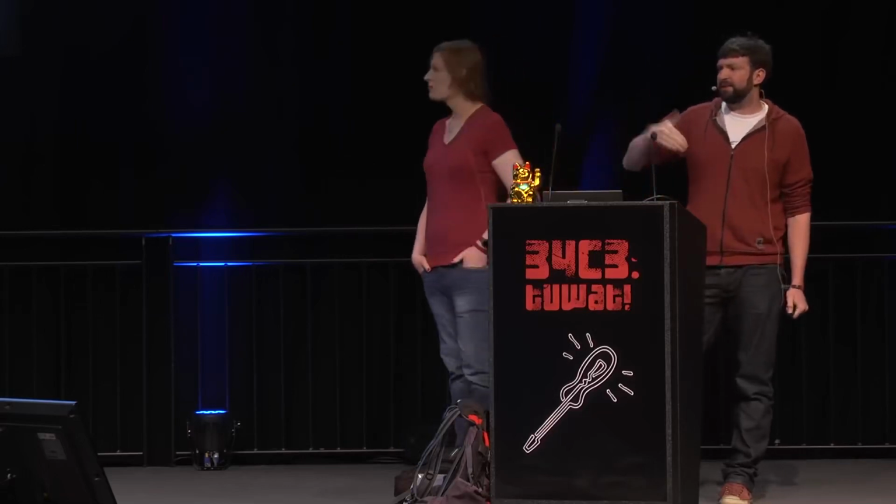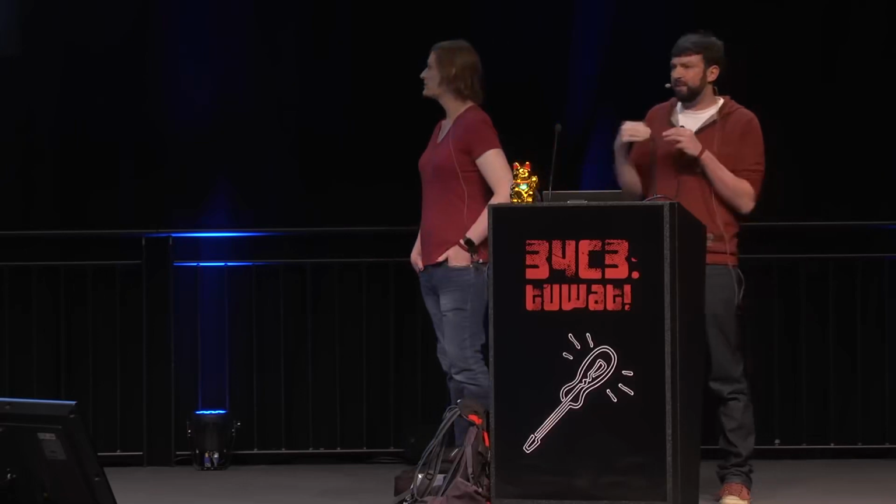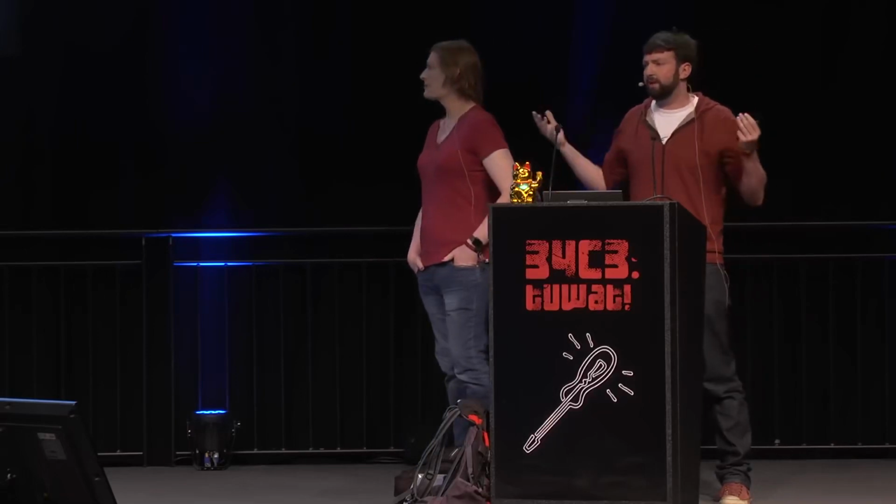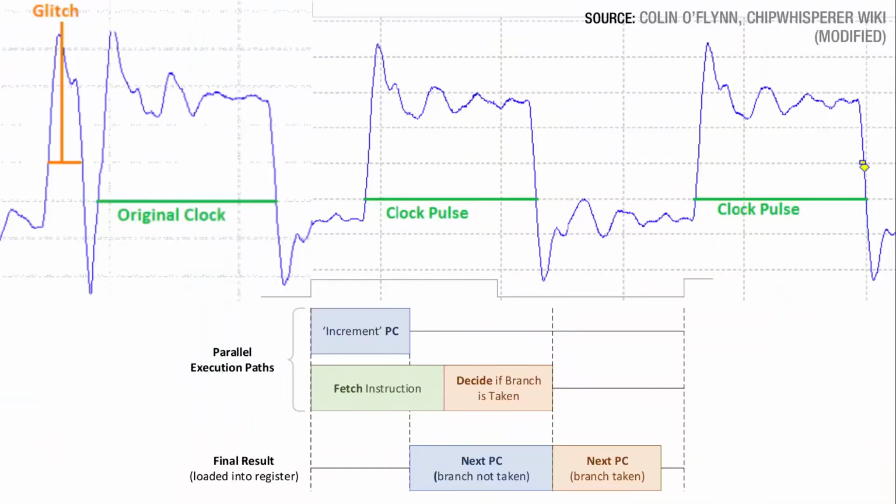And so we can do things like have the instruction pointer increment, and then the result of whatever that piece of computation is doesn't go anywhere. It just doesn't happen. And then on the next pulse, the program counter is exactly where it was, but the previous instruction didn't happen. So if that previous instruction is a jump, we've now just moved over it in the code. Happy? We can move on?